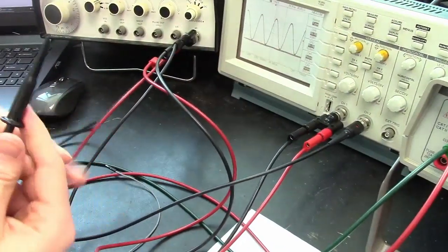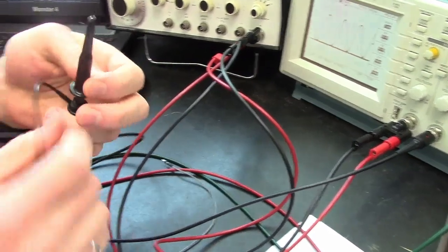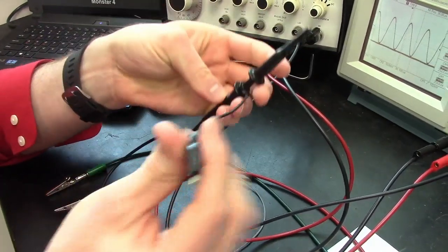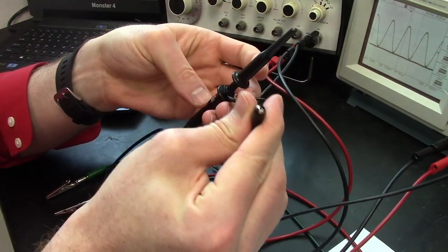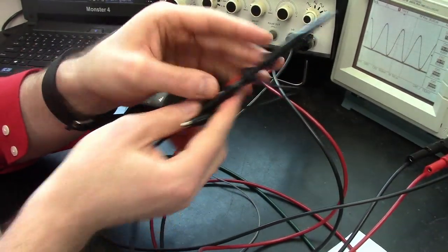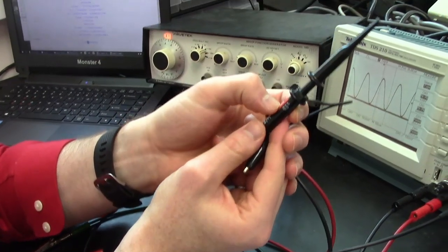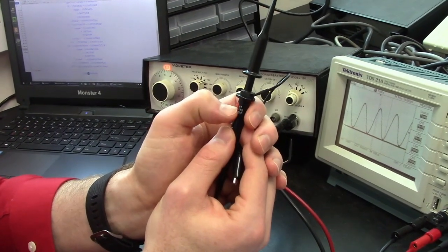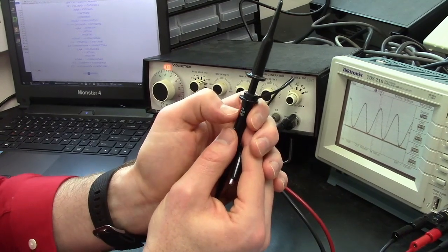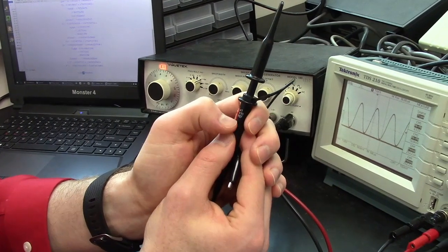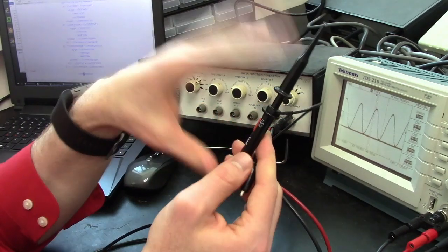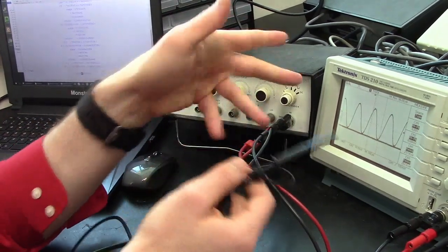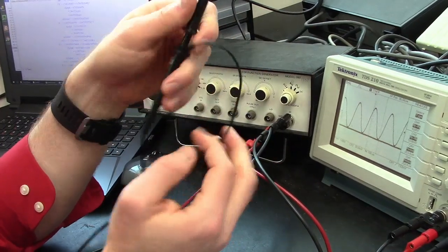And this has 2 different connections on it. It has an internal one, which is connected to the inside pin of this coaxial cable, and it has a clip, which is connected to the outside pin of the coaxial cable. You can put the scope probe on 2 different measurement modes. So you can put it on a 1x mode or a 10x mode. If you put it on the 10x mode, then it cuts down the signal that it's measuring by a factor of 10 before it shows up on the scope. So you're going to see a much smaller signal there.